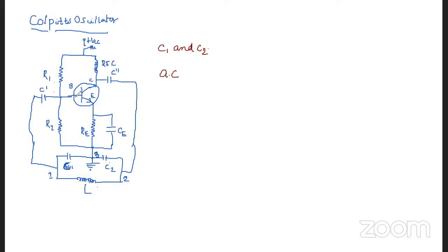Once the key is switched on, the capacitors C1 and C2 are charged fully. Then they discharge through the inductor, which makes an oscillatory current in the tank circuit, producing an AC voltage across C1.